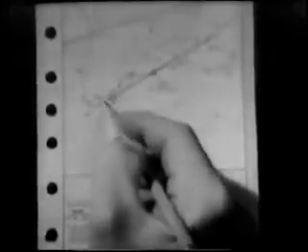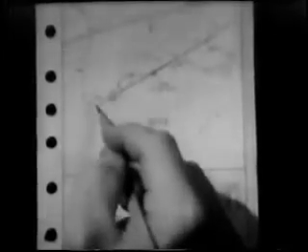The student seems to know the tuning procedures. Now he will check the approach chart for Cairns as the instructor gets permission from Cairns Tower to make a practice approach. Cairns Tower has given permission to work the facility. Notice that the approach course is the 241-degree outbound track. The procedure turn is to the north, and the published procedure turn altitude is 1,400 feet. The low cone minimum altitude is 900 feet.